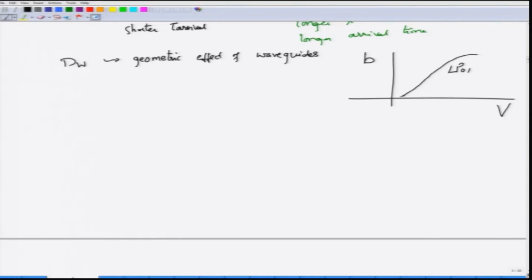So this is how, if you remember, the normalized propagation constant versus the normalized frequency for the fundamental mode would go like this. This is for the LP01 mode. You see that there is this curvature for the propagation constant, and this curvature is the direct result of having a certain core radius, a certain core cladding interface. So it is actually the geometry. Now if you turn around and make a rectangular type of optical fiber, then the B versus V curve will not be like this, it will be different.